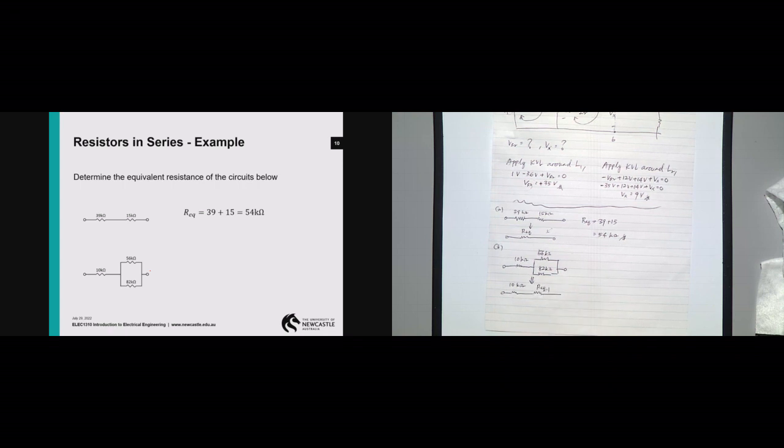I crack it down to a smaller R equivalent. I call it R equivalent 1. For R equivalent 1, you need to apply Kirchhoff's current law, or you can use the equivalent resistor formula right away, which gives us 1 over 1 divided by 56 plus 1 divided by 82.